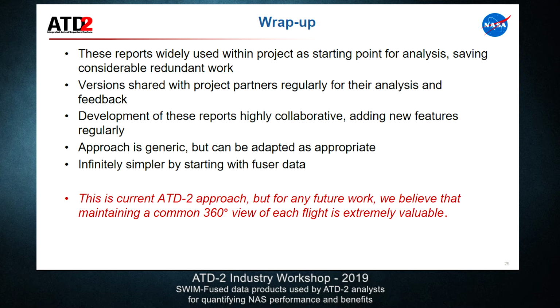That's in this predictive world. But after the fact, we have an actual taxi time, and again we have what we think is an unimpeded taxi time. We then take the actual taxi time and subtract the unimpeded taxi time and get what we would call the actual time in queue.